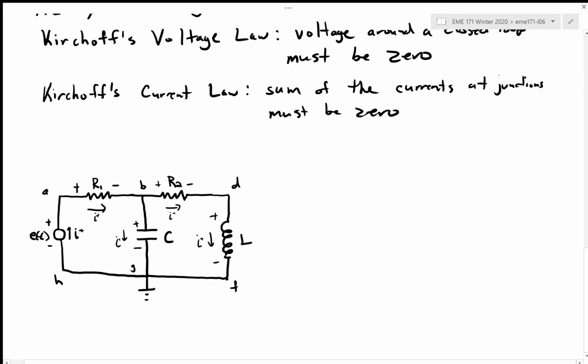Now we can start to develop the bond graph. Step 2 is to add a zero junction for each electrical node that has common voltages. Right? So I've got A, B, D, F, G, and H labeled. I am going to add a zero junction for each of those.